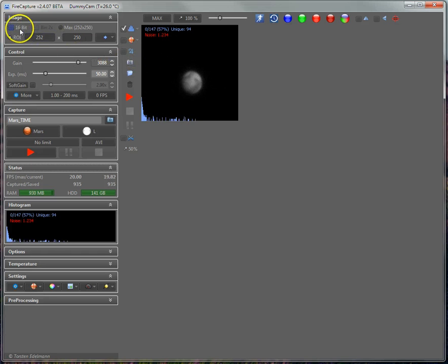So this is just a help, an indicator of whether the noise level you currently have is low enough that it would be a benefit to switch to 16-bit mode. That typically depends on the gain level, and whenever you see that the noise level below 2 turns red here, it's an indication that you would have a benefit to turn on 16-bit mode.